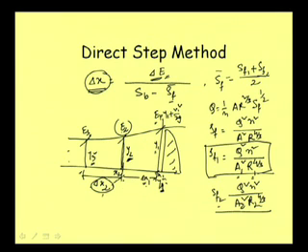And if it is M1 profile, suppose first we are calculating what is yn and yc, and we are getting suppose this is M1 profile, then we know that this profile will be extending up to normal depth yn. So we can keep on computing this one. Suppose this yn value is, we know that yn is equal to suppose, okay, let us say 5 meter, and this depth is suppose 10 meter.